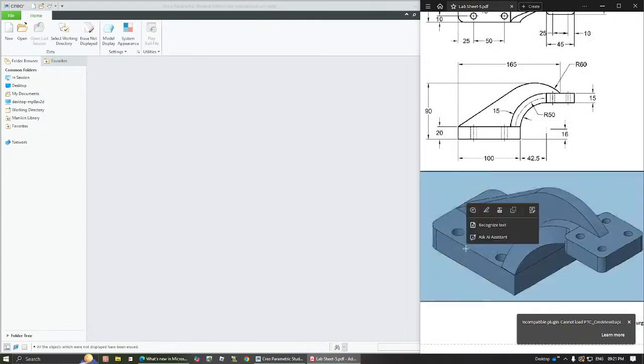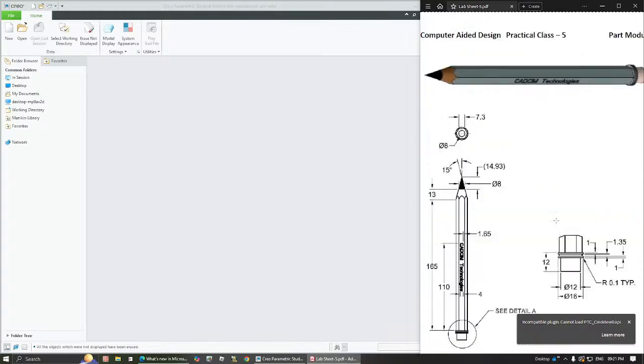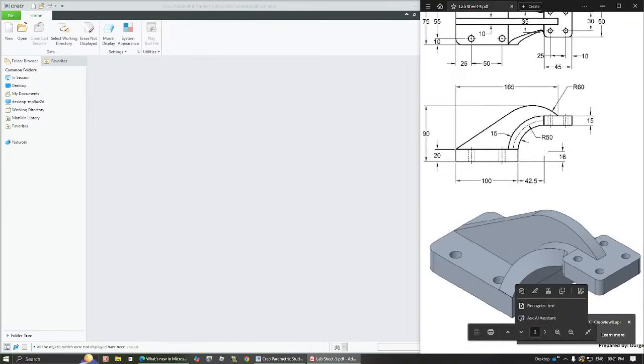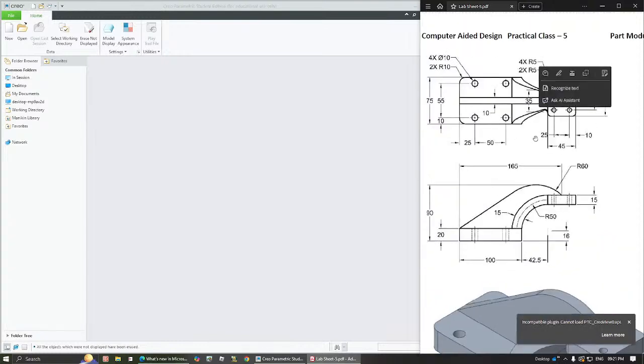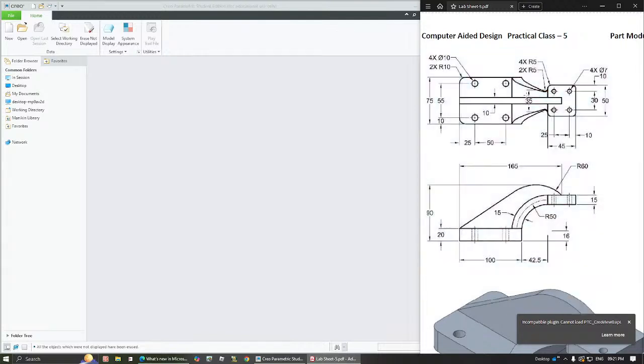We have an extrude over here at the bottom, the base, and we have another extrude over here. And these two extrudes are connected by this shape, which is slightly more complicated. When we see the shape, there is a sweep along the central line of radius 50. The bottom cross section is matching up with the width of the base, and the top side is having a total length of 35.